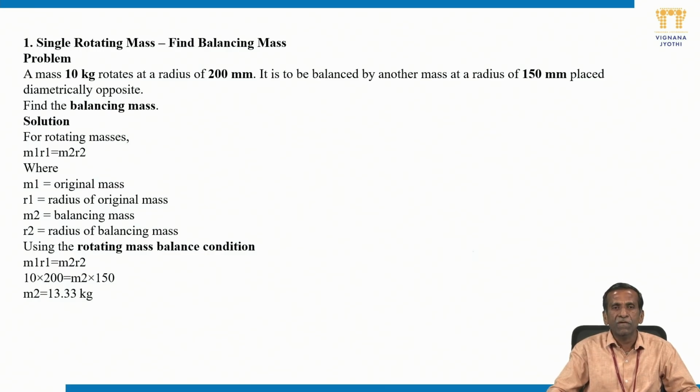If there is only a single rotating mass, we need not worry, because for force balance the algebraic sum of the MR products must be 0. Obviously, with a single mass it should be balanced with the corresponding mass and radius product. We can do this problem directly, without graphical or analytical approach. There is no point in talking about the graphical approach for this simple problem.